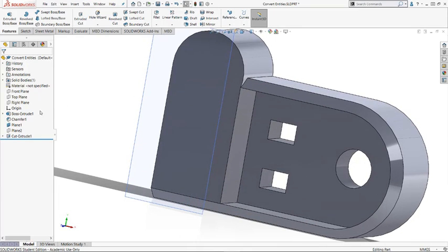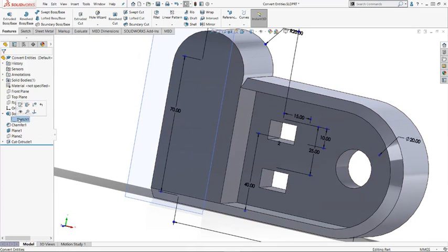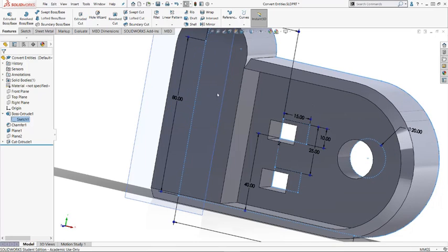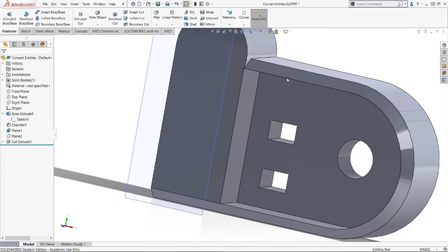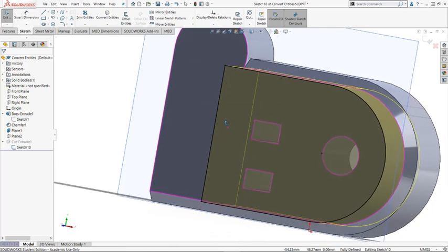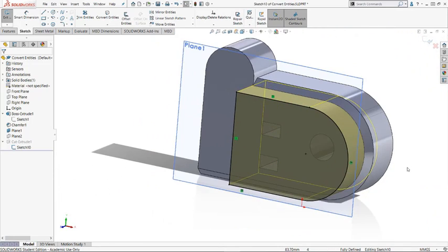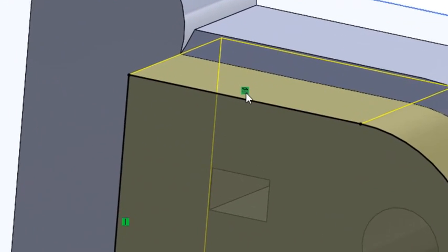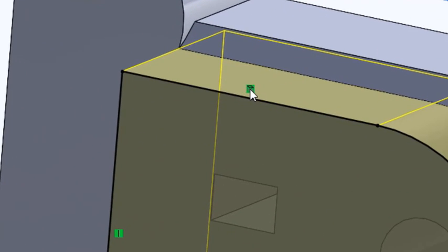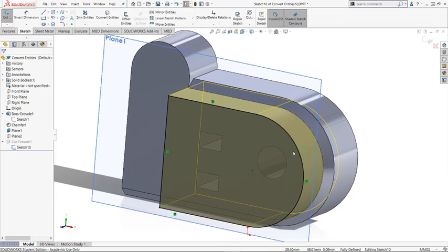If I go back to the original sketch, and if I change the dimension 70 to 80, that cut sketch is automatically adjusted to match the changed geometry. So that is the constraint. Actually, you see that convert entity constraint. So this sketch follows whatever the existing body changes.